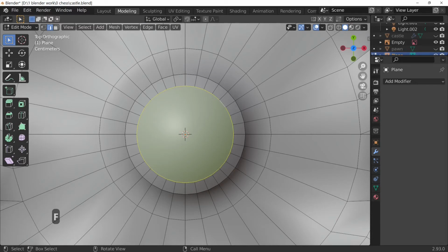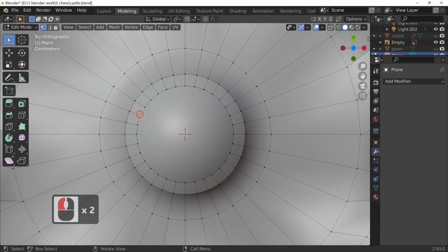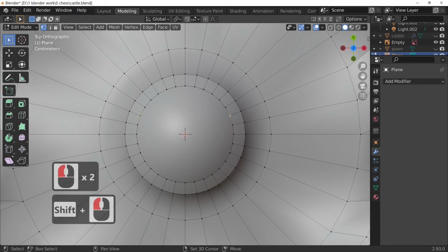Now that I've made a face, what I can do is select similar, that's the line across the axis from left to right. So I'm just going to go 1, 2, 3, 4. I'll make it 1, 2, 3. So from the center, 1, 2 up on that side, holding the shift key down, 1, 2, and I'm going to select that one as well.